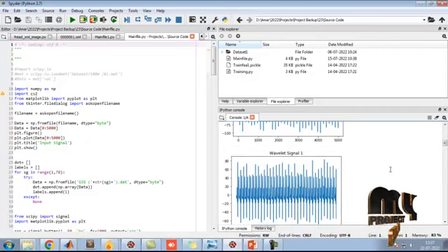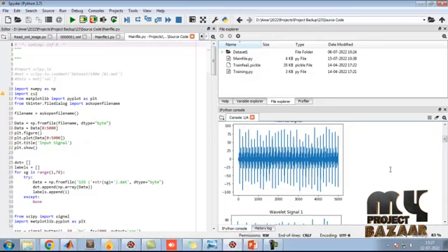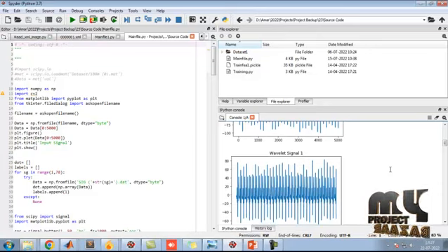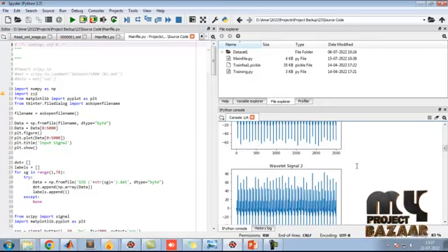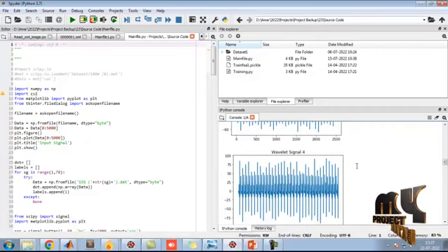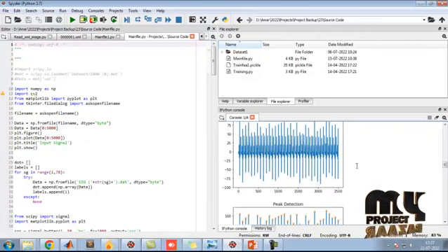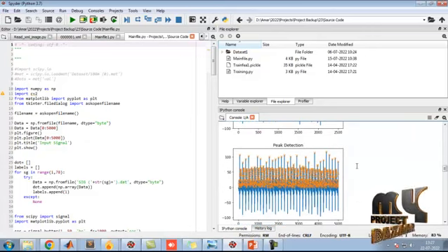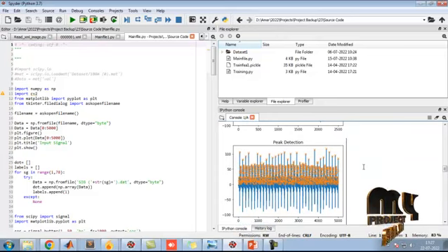Once the signal length is optimum, we can neglect it, or else if the signal length is too long, we can limit the signal to 5000. After the signal limitation and filtering, we move to the feature extraction. Before that, we are segregating the signal into wavelets like wavelet signal 1, 2, 3 and 4. This represents the wavelets of low frequency, high frequency, low frequency, then high frequency. After extracting the wavelet characteristics, we have to detect the peak ranges.